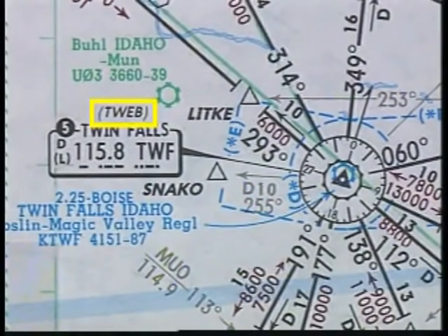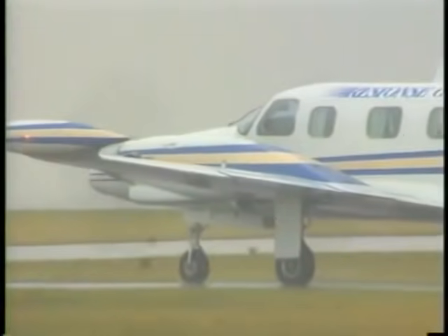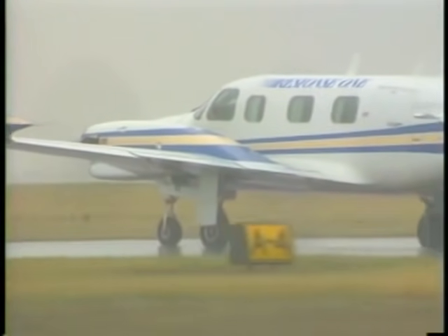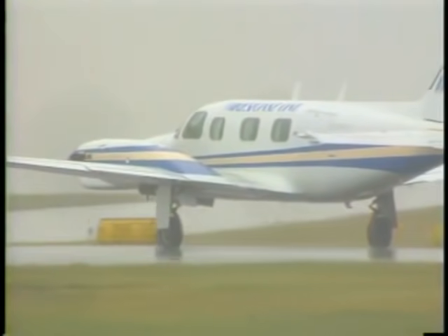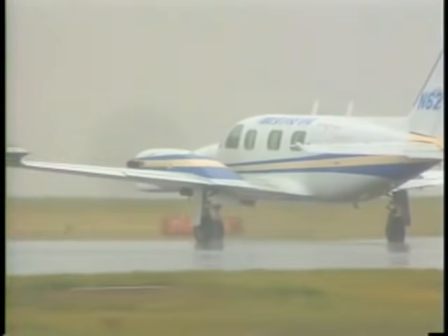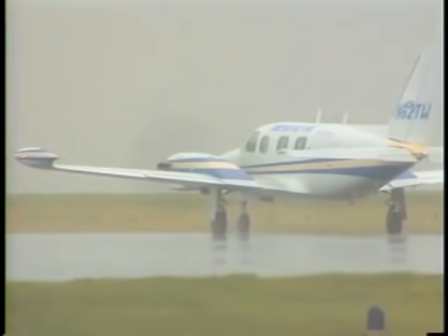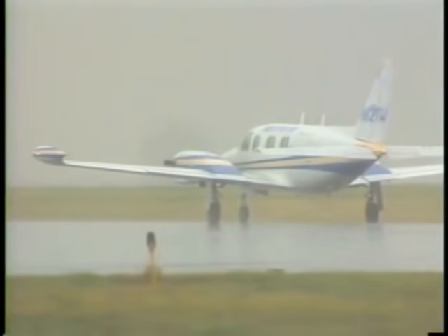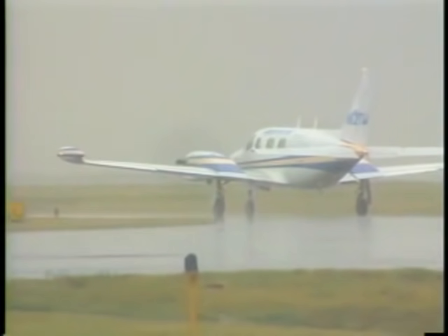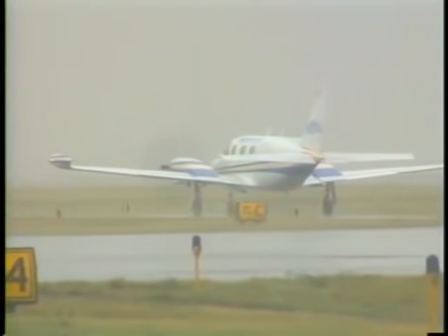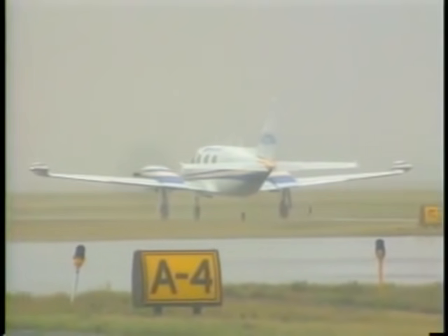The letters TWEB signify that transcribed weather broadcasts, or TWEBs, are available through this facility. Selected VORs and NDBs broadcast continuous weather information over the NavAid frequency. TWEBs consist of recorded tapes giving local weather conditions, along with general forecast and route information for the area. Although the information varies, the broadcasts generally contain route-oriented in-flight advisories, winds aloft, current weather reports, NOTAMs, and weather notices.